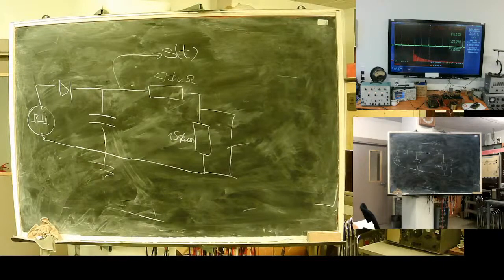It's a problem: large wafers of high power semiconductors are quite sensitive to high frequency components, because a high frequency component is not distributed evenly. At a low frequency, current distributes evenly on all the surface. At a high frequency, this distribution is not even. It's a kind of wave, and you can find a so-called hotspot where this semiconductor structure is overloaded. It overheats and degrades.